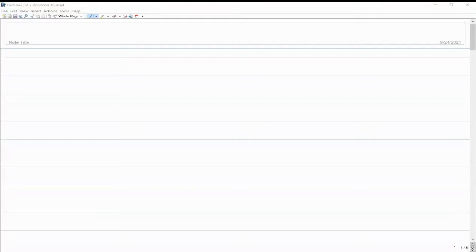So you look at W by H, where W is the maximum displacement, and H is the thickness. If that is approaching unity, say 0.5, 0.6, 0.8, then it would be a large deformation problem.